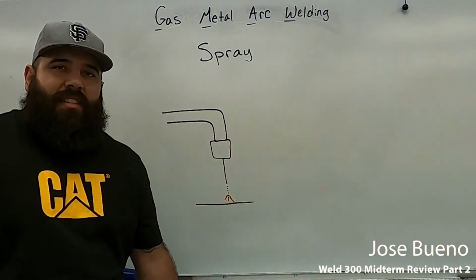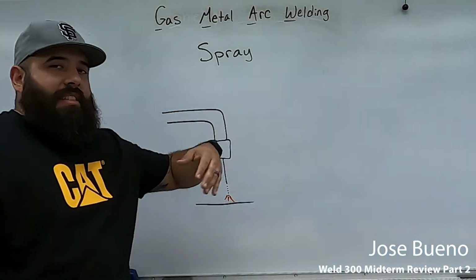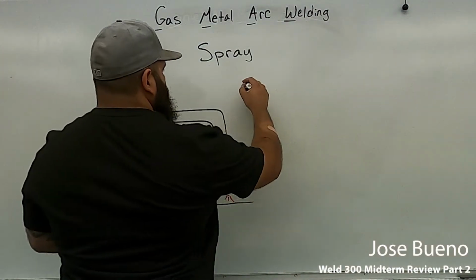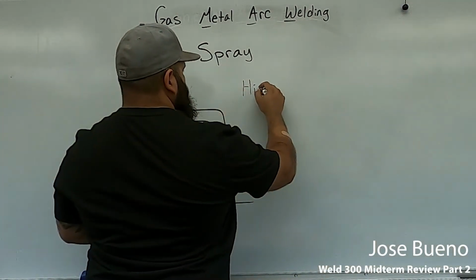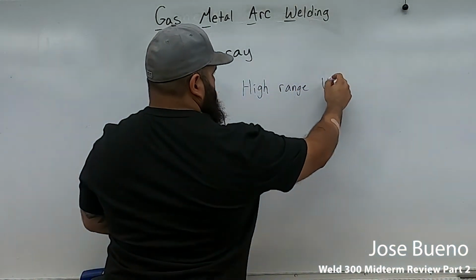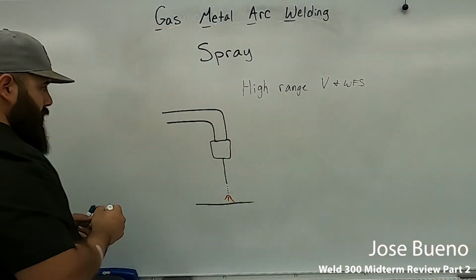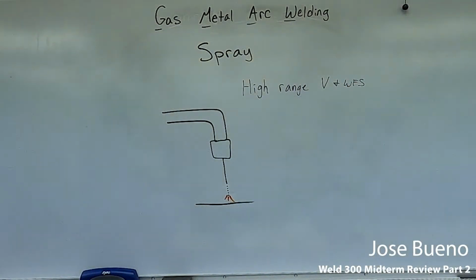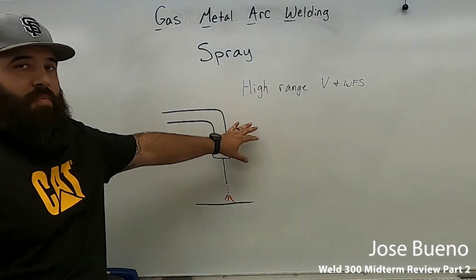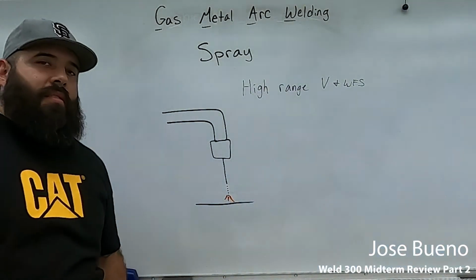So a lot of places out in industry will use spray mode because it's at the higher end, the higher ranges of volts and wire feed speed. So we can get better penetration using spray over globular and short circuit.